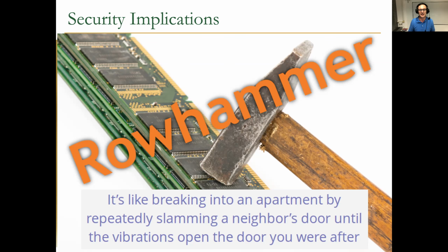Fundamentally, this is a disturbance error, and I think people at IMW are very familiar with disturbance errors. The difference with disturbance errors in DRAM is they're directly exposed to the programming language, operating system, and application. As a result, we're having a lot of trouble with these security issues that are caused by these disturbance errors. It's very different from disturbance errors in flash memory, for example, where you can prevent or fix these errors at the flash translation layer using heavy error correction codes. But DRAM doesn't operate that way today.